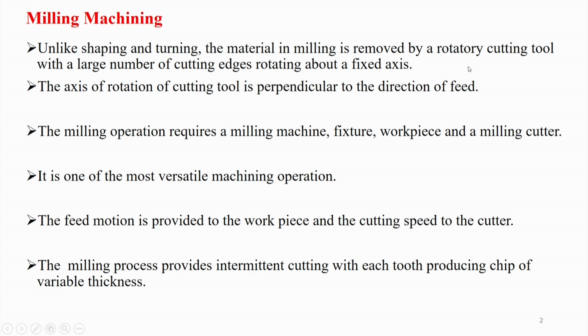by a rotary cutting tool with a large number of cutting edges rotating about a fixed axis. So, there is a cutter in which there are a number of teeth. The axis of rotation of the cutting tool is perpendicular to the direction of feed, and a milling operation requires a milling machine, fixture, workpiece and a milling cutter.